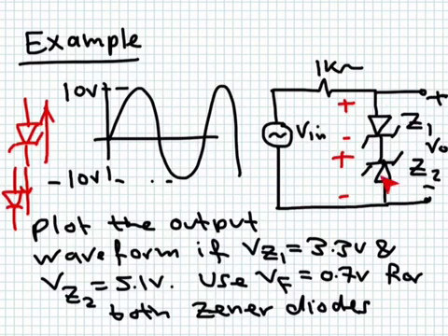in this direction. Okay, so you can see here we have a case where two active devices connected together, and they can both conduct simultaneously only if they are in two different regions. One of them, which is this one, will be in the forward region, so it will have a drop of 0.7 between the anode and the cathode.